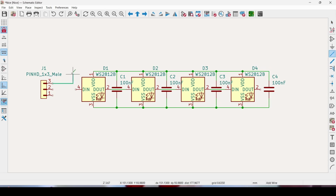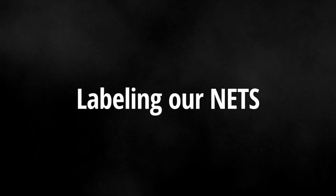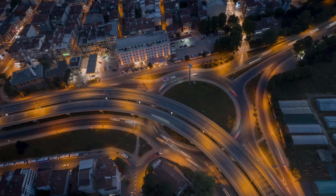Now we're going to go ahead and connect the 3 pins to the LEDs. If you're having a problem with your wires not routing the way you want, you can click mid-route to lock the wire into that point so you can get more intricate with your routing. So now we can go ahead and start labeling our nets. And nets are basically all the interconnected paths that our power, ground, or signal would be going through.